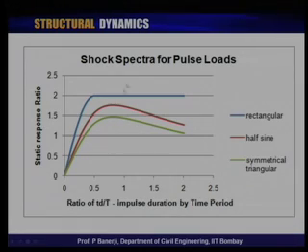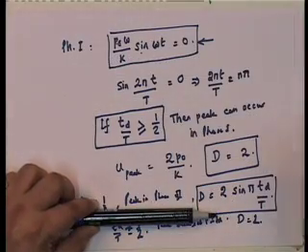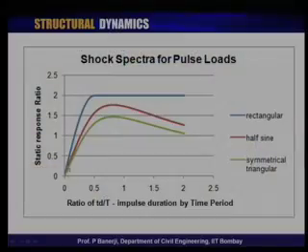So, in other words, the shock spectrum replaces the mathematics. Over here I have done the mathematics, but if I had this, I did not need the mathematics. If someone gave me the shock spectrum, I could look at it and say, oh, okay, this is my duration, read it, that is the duration.